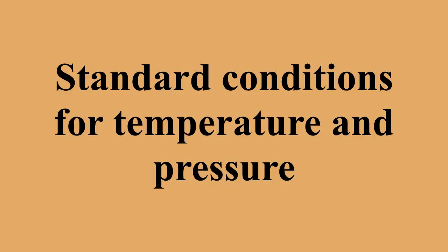NIST uses a temperature of 20 degrees Celsius and an absolute pressure of 1 atmosphere. This standard is also called normal temperature and pressure. The international standard metric conditions for natural gas and similar fluids are 288.15 K and 101.325 kilopascals. In industry and commerce, standard conditions for temperature and pressure are often necessary to define the standard reference conditions to express the volumes of gases and liquids and related quantities such as the rate of volumetric flow.